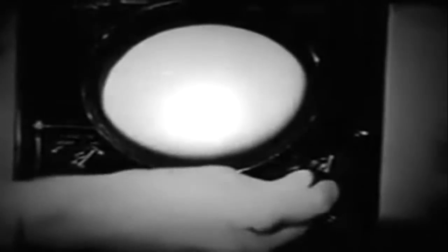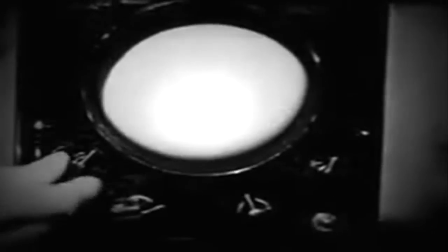At high speed, the persistence of the fluorescent screen plus the persistence of vision makes the moving spot appear as a line of light. The apparent extension of the line of light beyond the tube face is because it extends into the shadow of the shading ring. In the oscilloscope, the spot can be centered on the screen by these two controls, one for the vertical axis and one for the horizontal axis. These controls vary the amount of potential in their respective deflecting circuits.